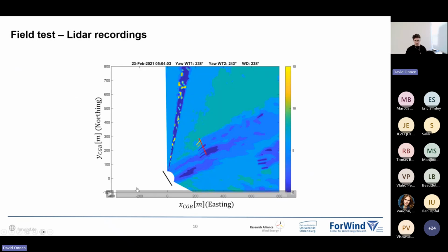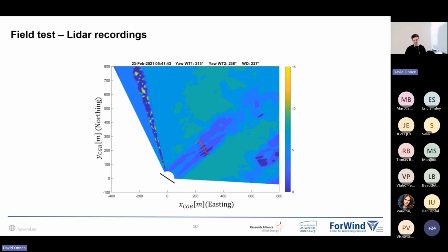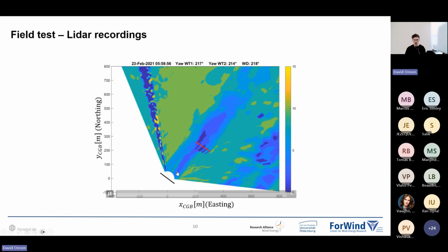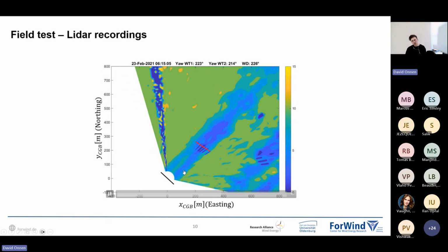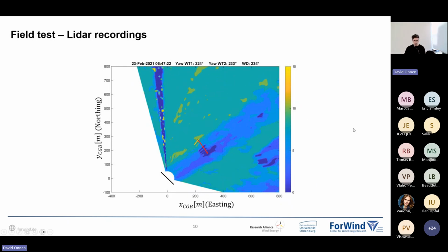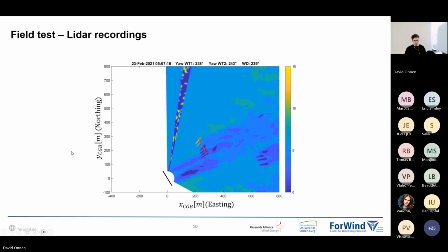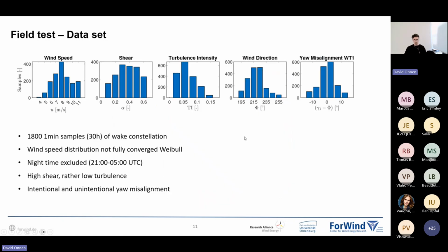If we look at the lidar measurements now, you can see here the 2 turbines indicated, upstream turbine in black, wake exposed turbine in red. That's how the time series looks like. So, recording. That's the level of insight that we get. So you also saw some yawing in there, sometimes misalignments. We see how the wake propagates, how it overlaps. That's the kind of data we are dealing with on the lidar side, and that we can use to reference our load-based control.